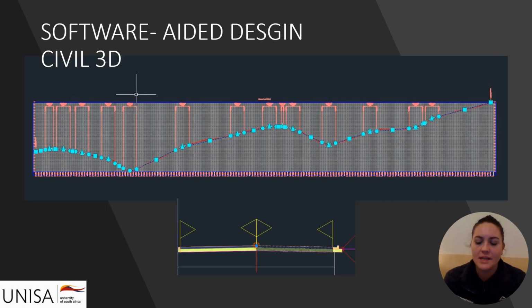From the alignment, I could create a profile. This profile will then be called the vertical curve. The design criteria, such as the curve length, is inputted into the program so that it automatically takes into account all standards set out. I can then move the design level on the graph and adjust the gradients of each curve so that it stays under the maximum gradient stated from the TRH17, which in this case was 7%.